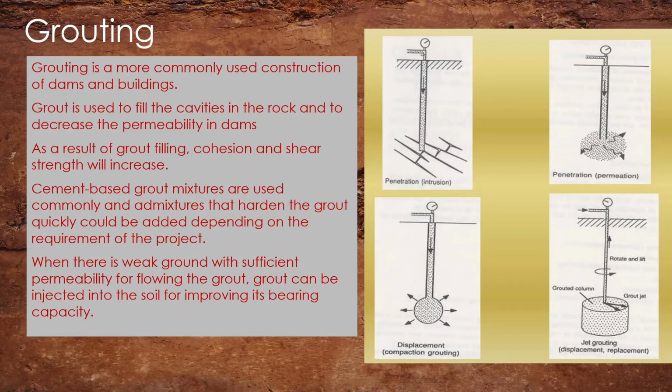So depending on the grout intake or the Lugeon value, you determine the Lugeon value to find out whether the cavities or the rock is taking the grout or not. Based on that, you will continue the grouting. What we have to keep in mind is that we have to control the movement of the water through the dam body.